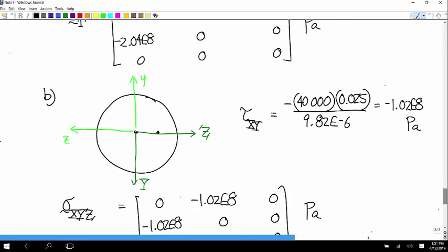What is the stress tensor due to torque? Okay, this is the last question, and then we're done. What's the stress tensor due to the torque for a point at the centroid? 0. That's right, because rho is 0, so none of the other stuff matters. Any questions? You will. Yeah.